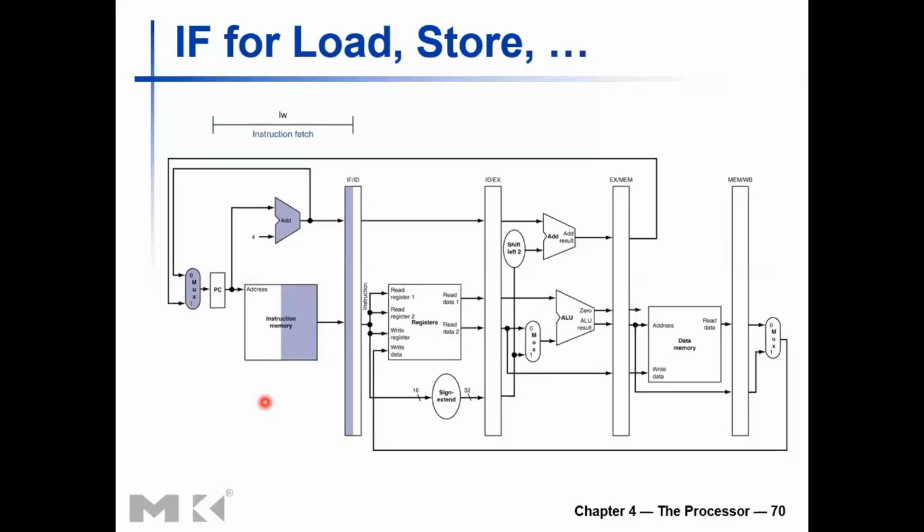So, right. At the end of this clock cycle, we have two pieces of information ready to be written into the pipeline register. That is the 32-bit instruction word and the 32-bit PC plus 4 value corresponding to the currently fetched instruction, right?